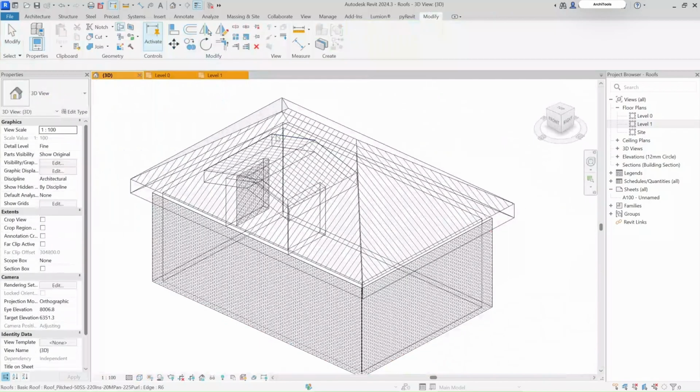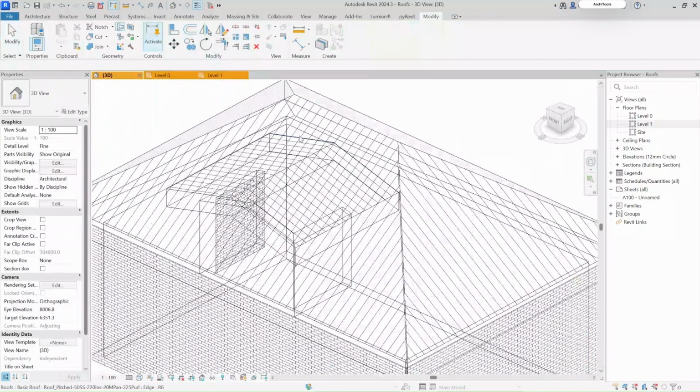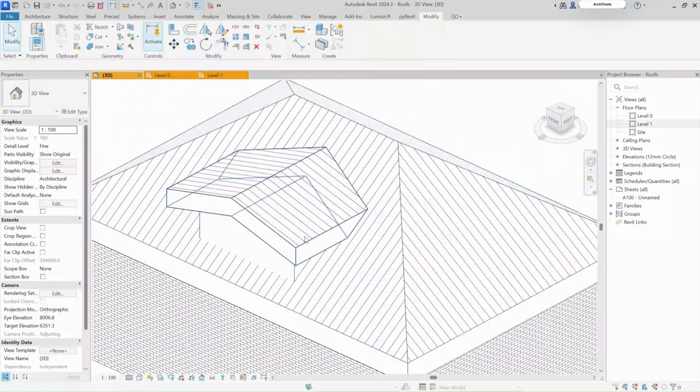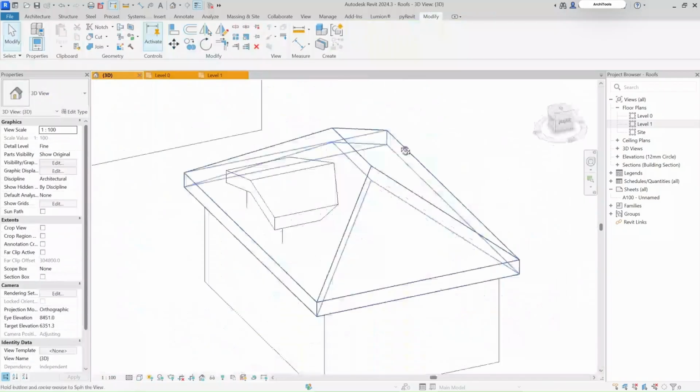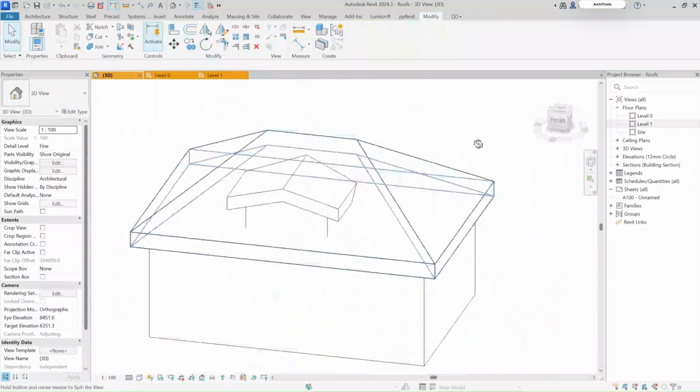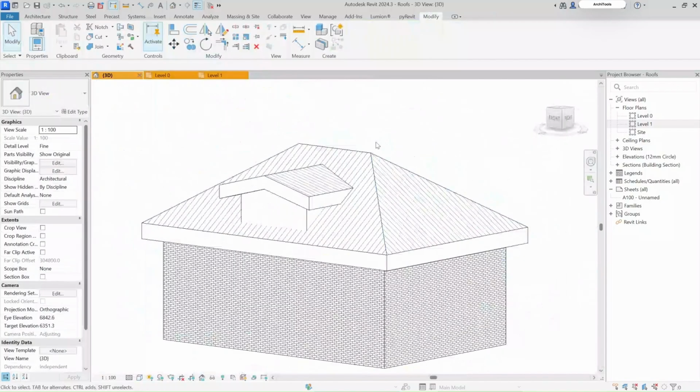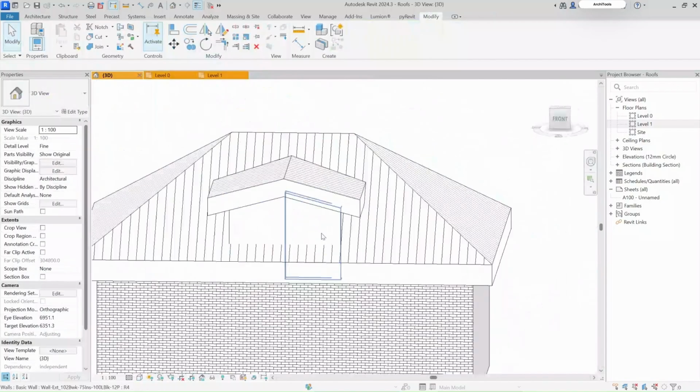Now you will get the edge of it, the smaller roof. Just select this, and next thing it will ask the face on the part you want to join. So we want this face. I'll click on this, and if you go to hidden line by clicking on HL, so this is how it joins itself perfectly smooth as we want it. The next part would be